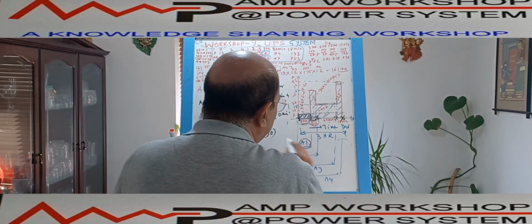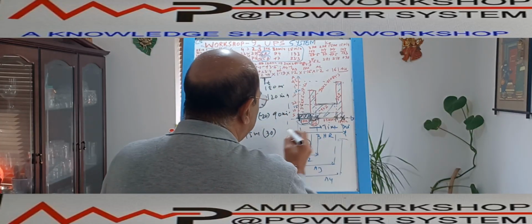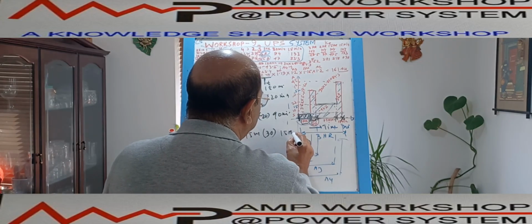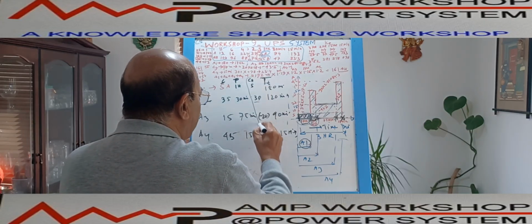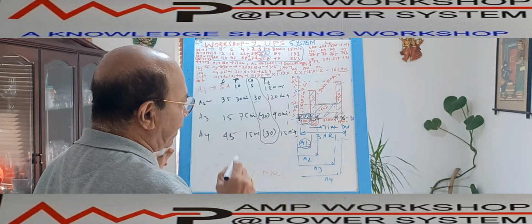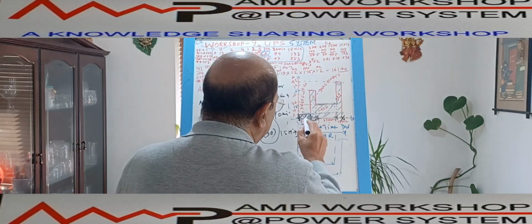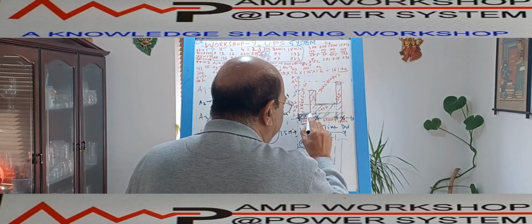And what is the T total? T total is from the start of this section to the end of discharge, so that is only 15 minutes. Okay, so this way we have to calculate the change of current. Why are we doing this? Try to understand: if I calculate only this area, that will not give the right figure, because the battery is already loaded with 5 ampere.